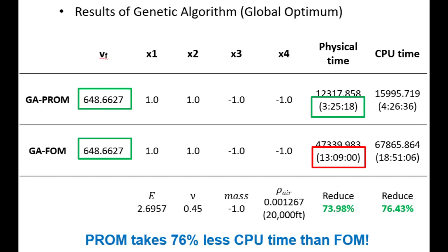Next, we use the 171 by 171 parametric reduced order model in flutter optimization. Flutter is a life-threatening situation concerning the flight safety and structural integrity of every airplane. It refers to a dynamic instability, in which the interaction between the flexible structure and unsteady aerodynamics is such that any small disturbance will lead to gradual and sustaining oscillation of the wing. At any airspeed slightly higher than the flutter speed, the wing will diverge and be broken catastrophically. Therefore, airplanes must be designed such that no flutter occurs within the operating flight range.